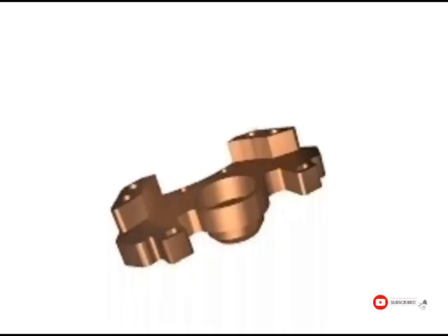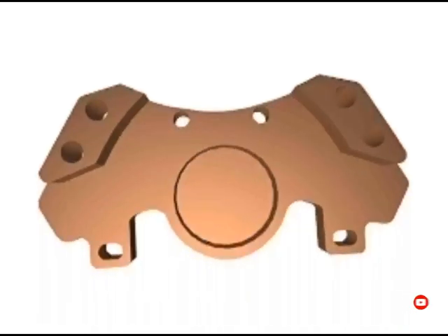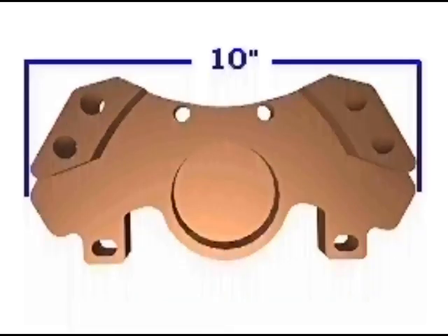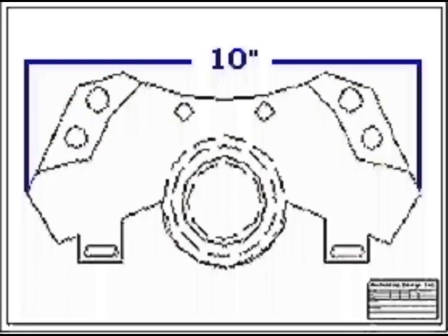In most CAD applications, you draw objects at full scale. This means that if a line in the real world measures 10 inches or 10 meters, you draw a line that is 10 inches or 10 meters long. It is only when you lay out a drawing in preparation for plotting that you set the scale for various views of the model to fit on the drawing sheet or layout.